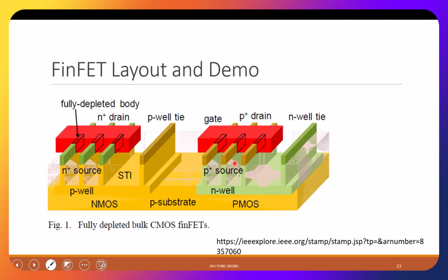And on the same structure, we also have P-type. And because it's about FinFET, they need to bias the P-well, right? So they have a P-well type. But in the Cadence one, we don't need to do that. They don't have that. I think it assumes SOI. Okay, and same for here, you have the N-well, right?